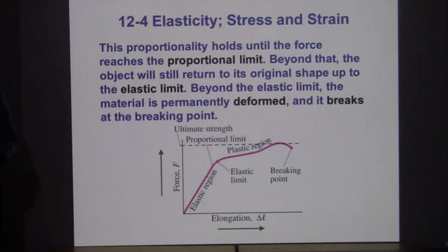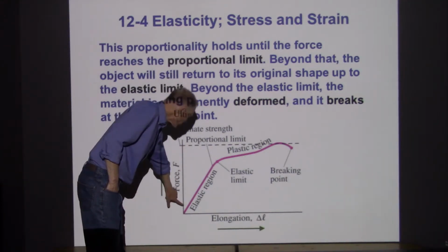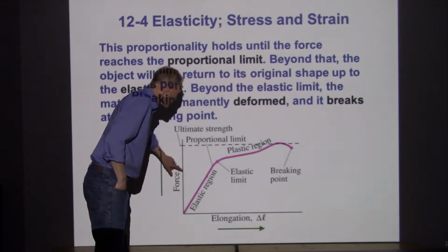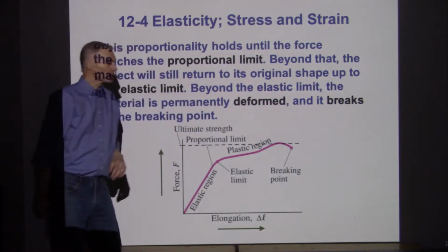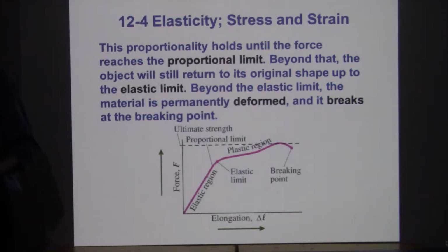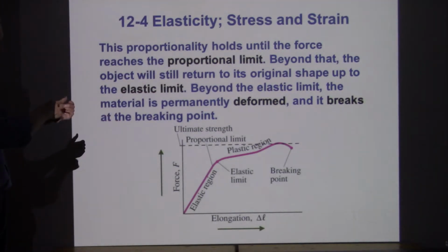What we can do is take a material and exert larger and larger forces on it until it fails, until it stretches out so much that it doesn't recover. And so there's what's called an elastic region. If I keep exerting a larger and larger force, what I find is roughly a proportional elongation. That's what the formulas we're going to be looking at will tell us: we'll get a proportional delta L. Delta L is proportional to the force being applied to the structure.